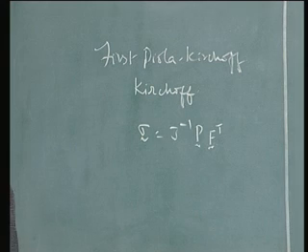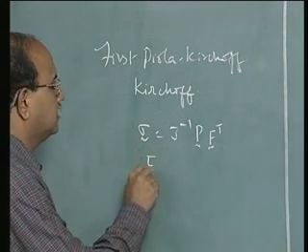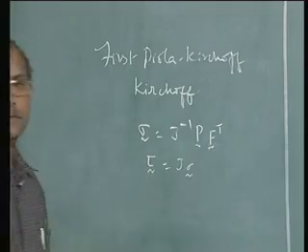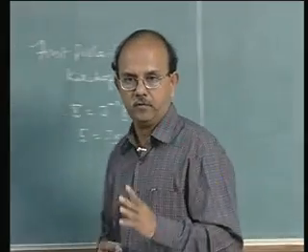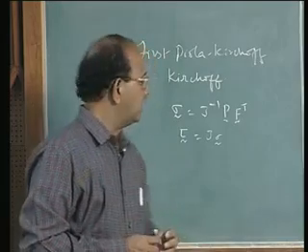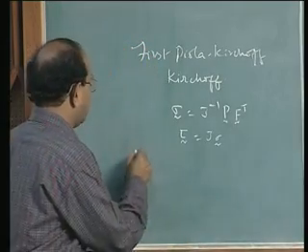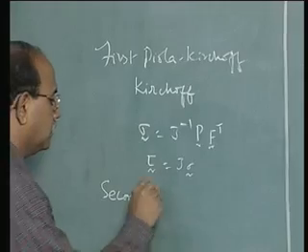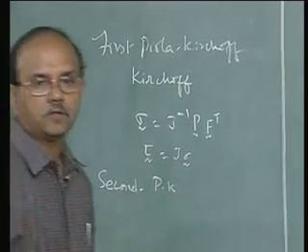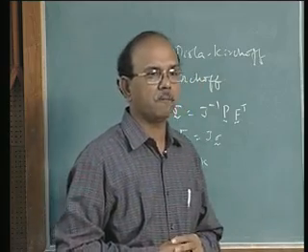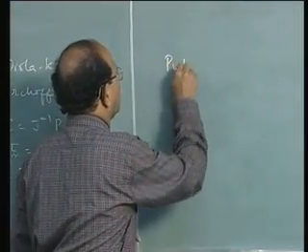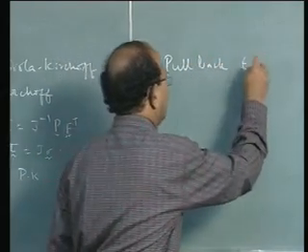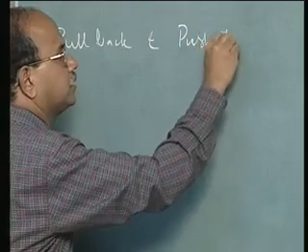And we said the Kirchhoff stress can be written as J sigma, and we also observed that the first Piola-Kirchhoff stress is not symmetric. There is another stress measure called the second Piola-Kirchhoff stress. But before we go to the second Piola-Kirchhoff stress, we have to understand a very important operation called pullback and push forward operations.